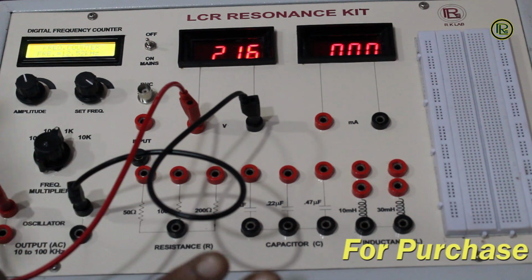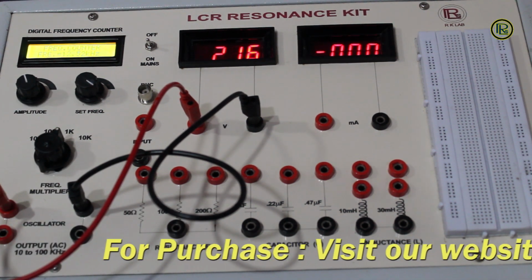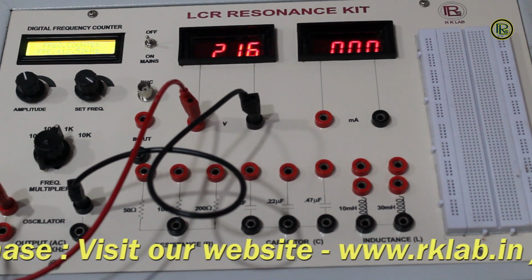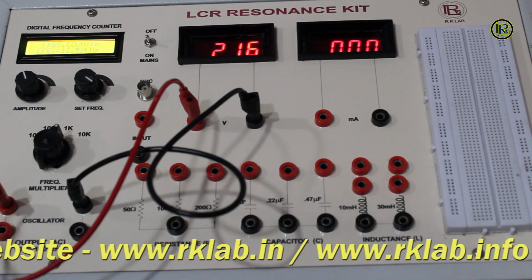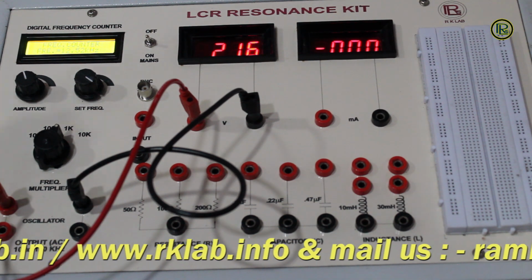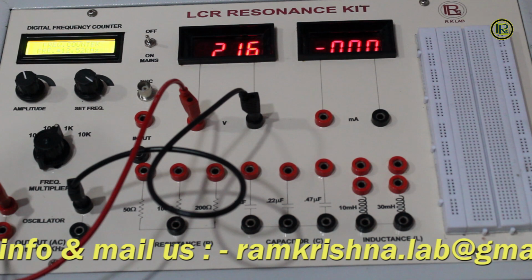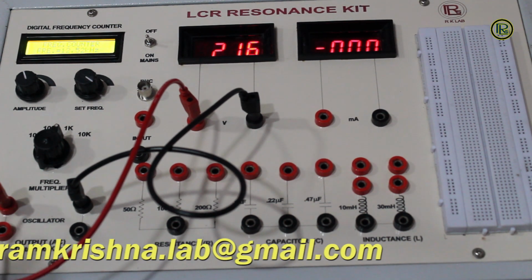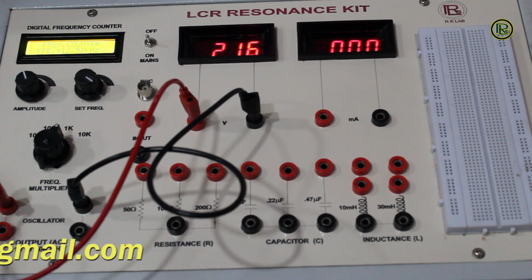So this is the primary thing that should be maintained, because I have to scan the frequency of the source to something like a few kilohertz. In that range, the amplitude of the oscillator should remain constant, so that I ensured. So if I change the frequency, then the amplitude remains constant. Okay, next part is I have to complete the circuit for series LCR.